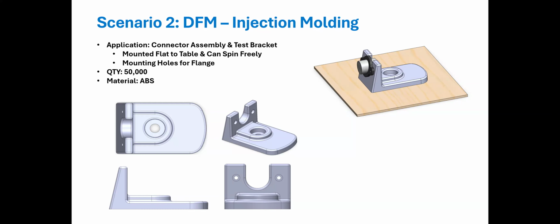However, when it comes to the actual design, what else could be done to optimize it for injection molding? Ted says material. All right, there you go. As we talked about earlier, there's a lot of unnecessary material to this part. We can basically cut this in half and save on the amount of plastic required to mold this part.